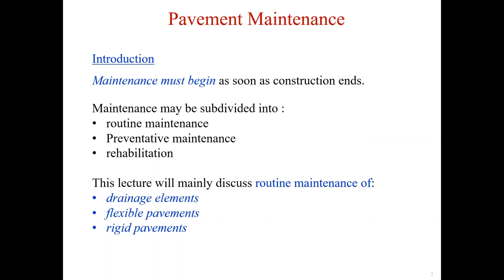Preventive maintenance includes works that are intended to reduce future deterioration by timely surface interventions, to limit the need for expensive rehabilitation, and to ensure minimum skid resistance and general safety levels do not fall below minimum accepted levels.